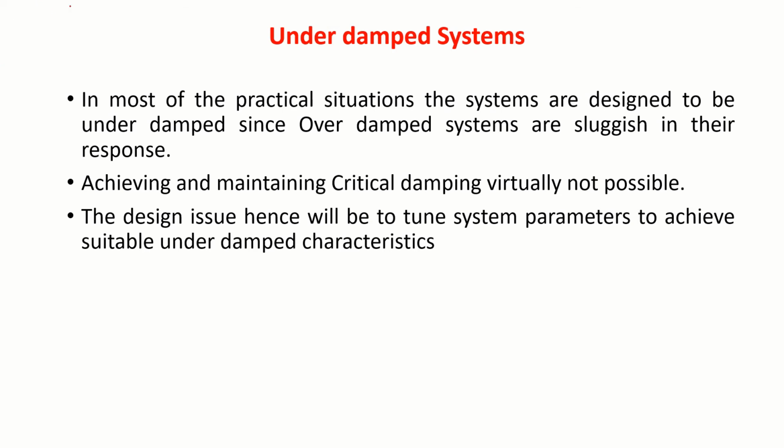So let us study the characteristic. In most of the practical situations, the systems are designed to be underdamped, since overdamped systems are sluggish in their response, you have seen that. Achieving and maintaining critical damping is virtually not possible. So the design issue hence will be to tune the system parameters to achieve suitable underdamped characteristics. What it means we'll see now.